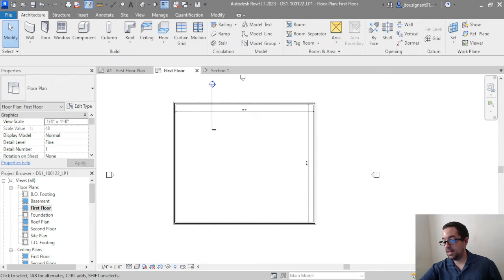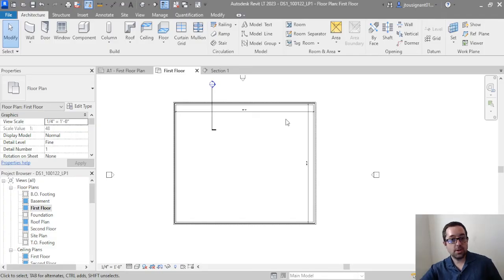I'm going to say this for many of the tools, that having it on or off isn't necessarily right or wrong. It's going to be contextual to what you want. If I'm picking a bunch of walls, I might want to have this off because I'm not wanting to select faces. I'm going to make sure that the wall is automatically snapping to the walls that I'm wanting. But if I'm wanting to select faces like windows or floors or doors or something that might not have a hatch on it, it is helpful to know that you can turn that on,